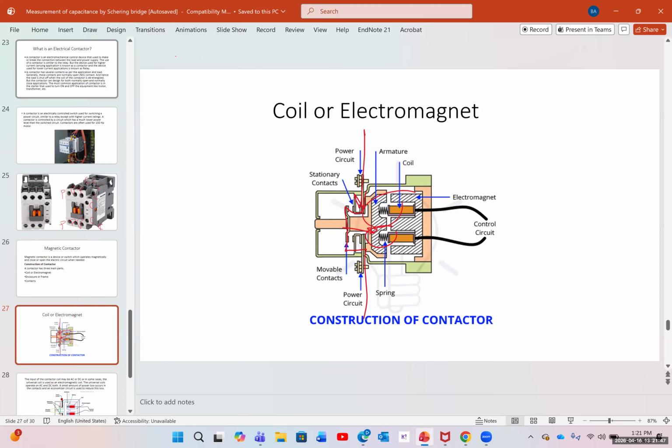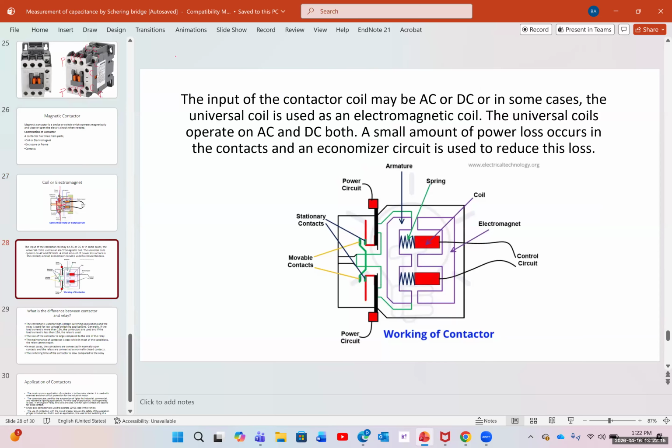You can immediately see some problems with these contactors. One problem is if you have very high currents and voltages, and you close and open them too fast, it's going to produce some electric arcs and fuse them together. So one point of failure is actually these stationary and movable contacts, which high power goes through. And we have systems to prevent them.